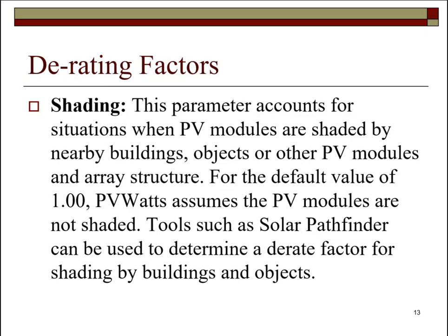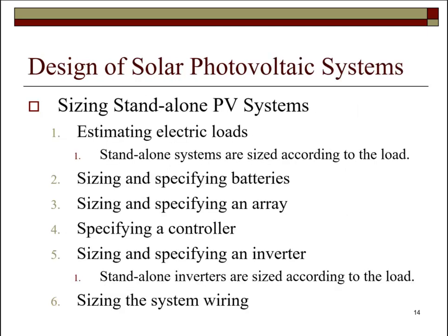Shading, covered in slide 13, is a special case and can reduce module array production significantly. A shading analysis must be completed on any site with shading. There are analytical methods to determine the estimated reduction in production. We will be performing these calculations in our next lesson.